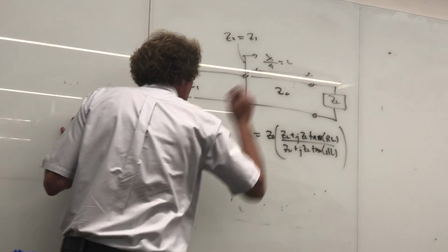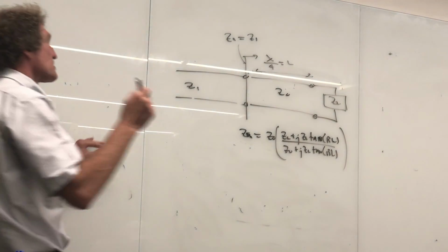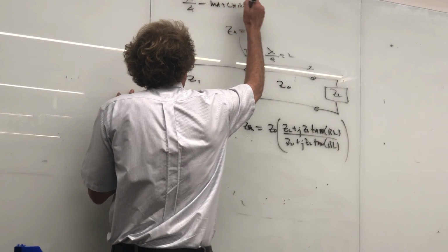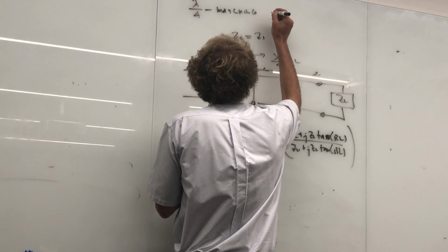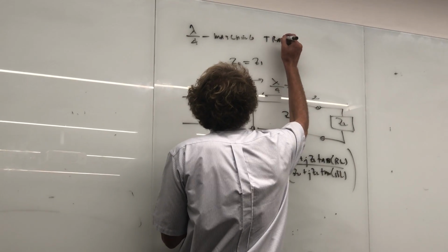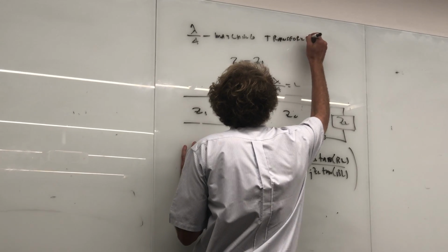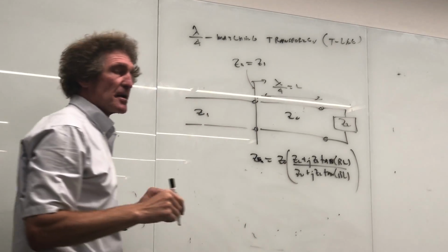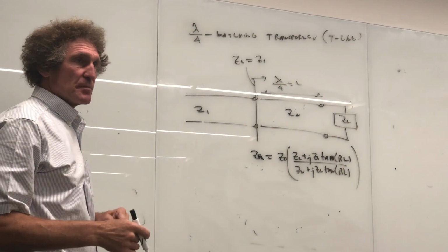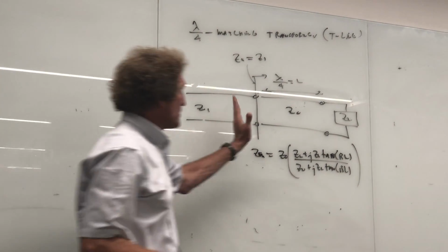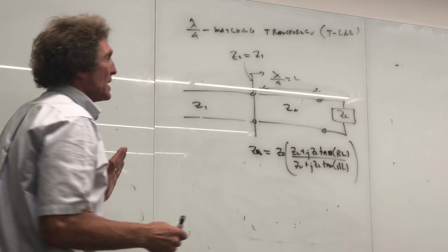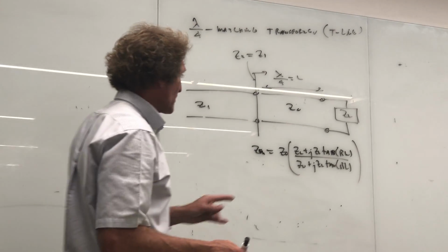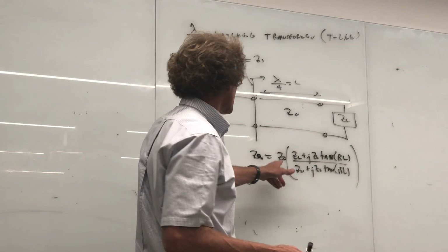Now that's a quarter wavelength long. I made that, and this is called a quarter wave matching. Really, they call it a transformer, but it's a T-line transformer. But you can just say T-line. It's a quarter wave matching transmission line. It's an old trick. And this only works for a single frequency because wavelength is a function of frequency. So if I cut a piece of line like that, and this is really one done more with fabrication.